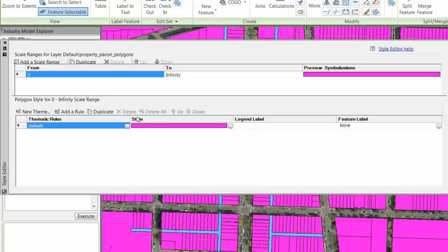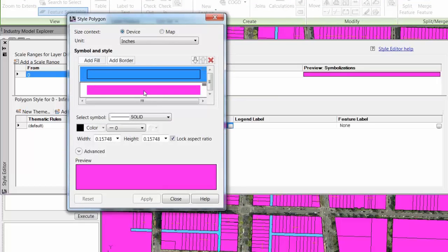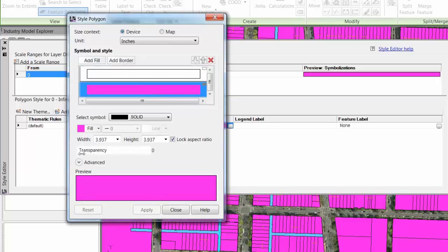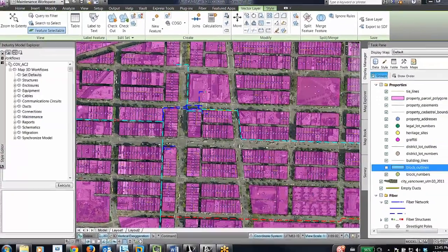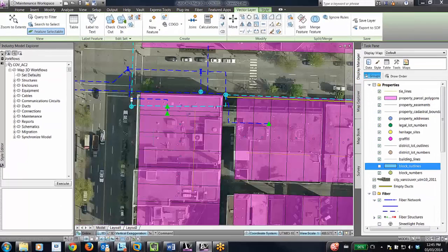If you click on the layer and select Edit Style, the Style Editing dialog box appears. This will be where the user can change how the styling is viewed. Select the style for the polygon, and there is a transparency property. This is changed to 50%, and then all the layers are visible underneath. With the layers visible underneath, external structures and physical markers can be seen with the fiber map.